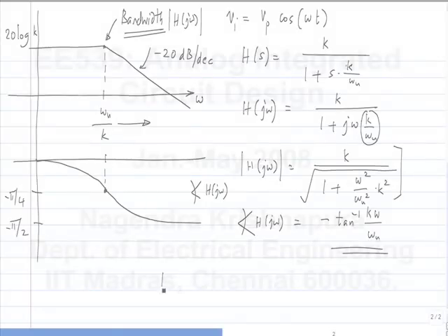So let's say I had K of 10 initially and I make it 20. What will happen to this? So what will the Bode plot look like? It moves up. So there are two segments in the Bode plot. What happens to each of those? Both of them will move up. So what happens is the DC gain increases and the pole reduces to half the value, right? And the slope of this is 20 dB per decade. So this line is the same.